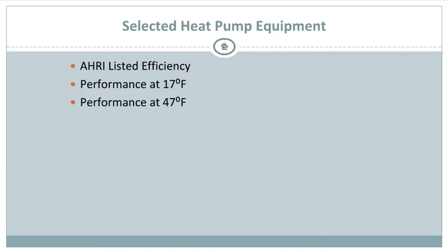Again, is the heat pump your best choice? Once you look at your Manual J and you do your Manual S and your Manual D and all this stuff, it might say a heat pump isn't going to be the best choice for you. It might be a split system. It might be a furnace with evaporative cooling, with another cooling system. So who knows? It all depends on what your Manual J determines for your area.